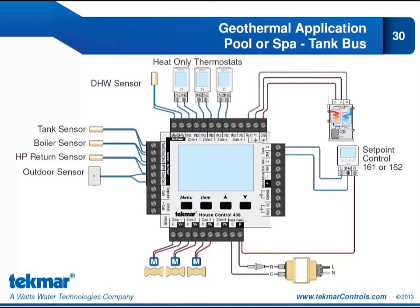So this is very similar to the previous example, except I have moved my set point control from the boiler expansion terminals to the tank expansion terminals because it's now on the tank bus. I've also made a note here that these thermostats will be heat-only thermostats. So I would choose a 552 because I'd only be doing radiant heating. I would not be doing radiant cooling. Otherwise, I would be sacrificing heating my pool for the summer months.